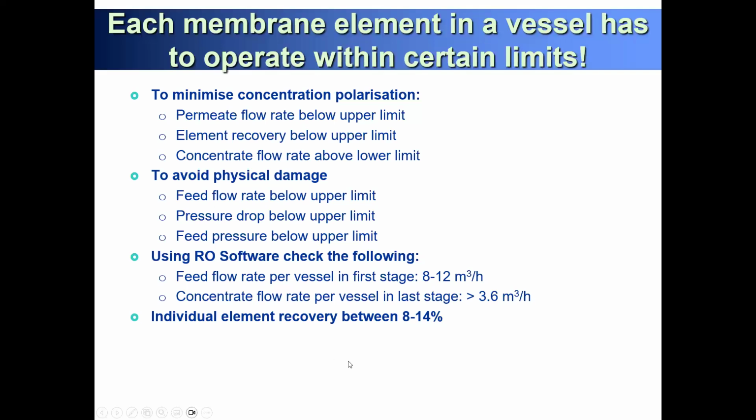Individual element recovery, yesterday we already tried. The first one is 12% recovery, the second one decreases to 10%, the third one decreases again to 9%, 8, 7. So it decreases a little bit from each element. So we always maintain individual element recovery between 8 to 14%. These combine together, and then finally you recover more than 50%, 60%, up to 90% of the water recovery.